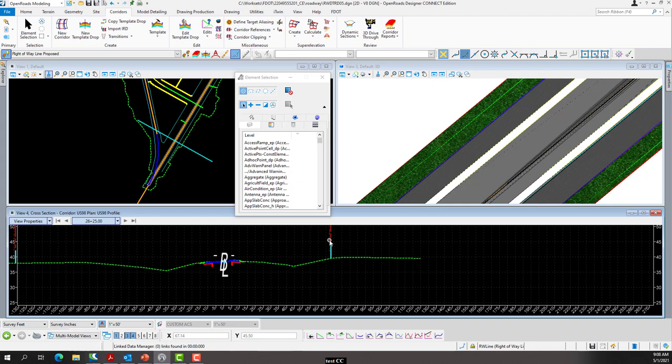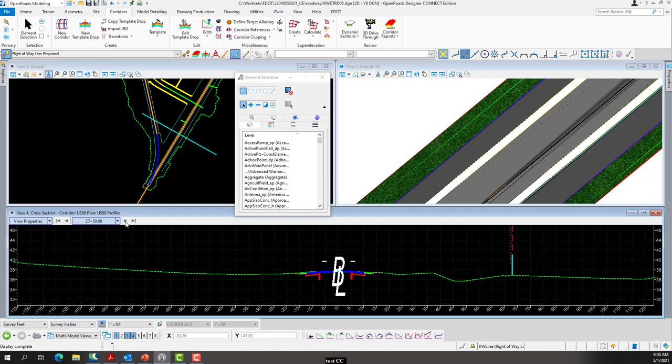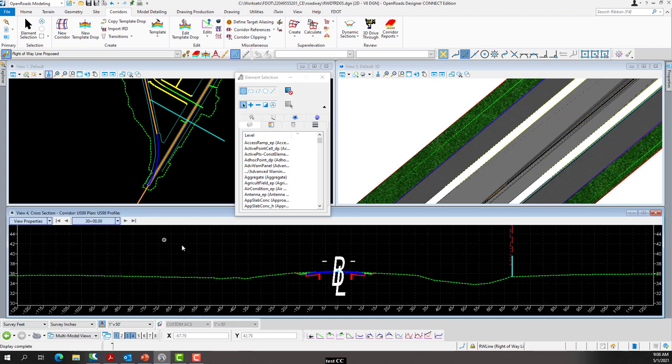So there's our right-of-way lines, and this is just a display of the two colors, which is okay. When you do have them in your cross sections for your sheets, they will display correctly. Let me go in my view attributes. I want to center on backbone and then walk through, so that will center on that backbone, and I see the existing lines there and walk through.